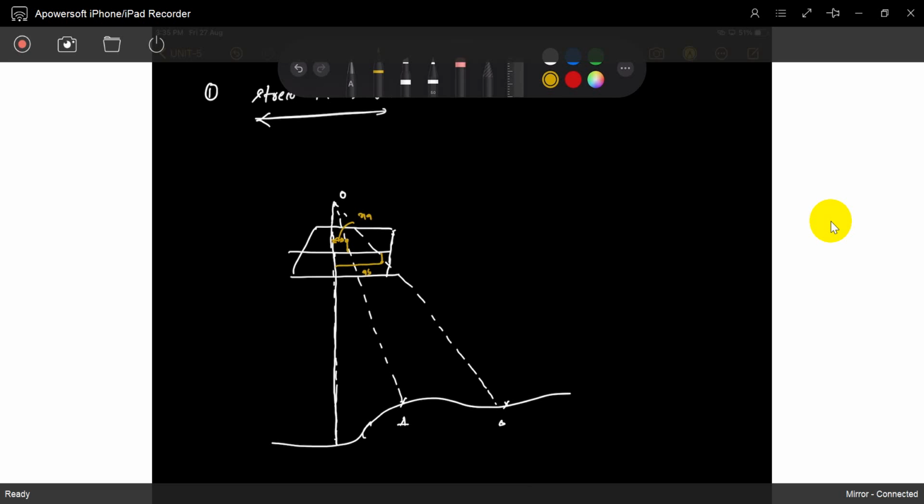So again, if you take it, we will observe the same points on the next photograph. This is the base distance, you can call it the base or the aeroplane base value. How much distance we take a photograph at is based on flight planning. We already discussed yesterday how many photographs are required to cover the total area. Based on that, you can easily find how much distance there is between any two photographs.